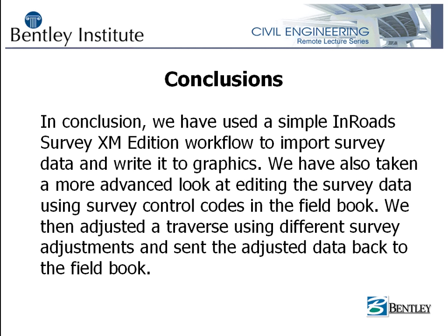In conclusion, we have used a simple InRoads Survey XM Edition workflow to import survey data and then write the different survey data to graphics. We have also taken a more advanced look at editing the survey data using survey control codes in the field book. We then adjusted a traverse using different survey adjustments and sent the adjusted data back to the field book. This concludes the presentation for InRoads Survey XM Edition introduction.